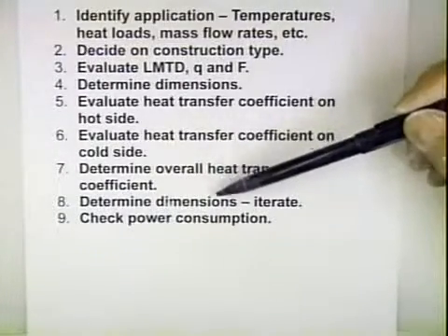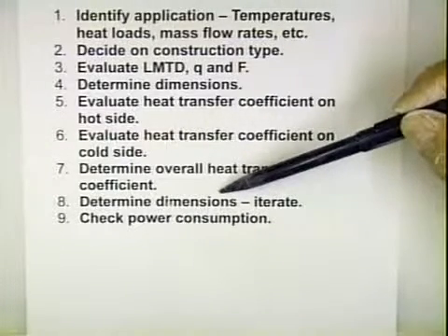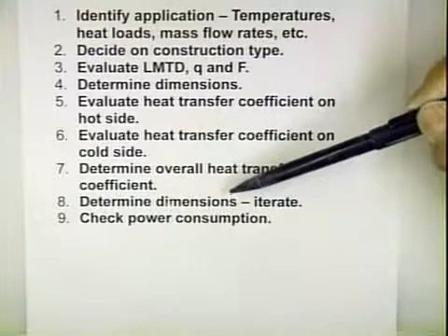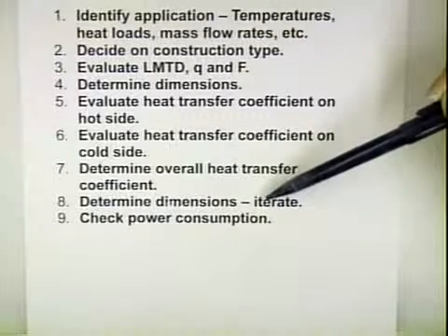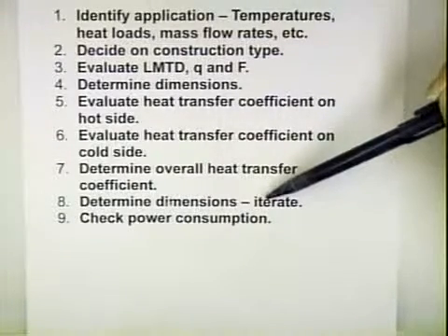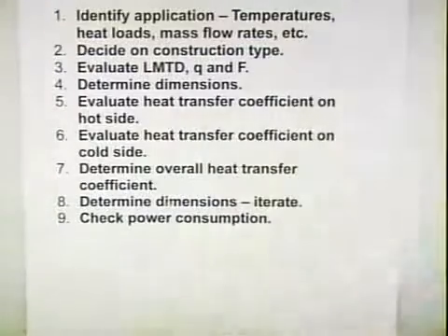Once we'd done that, it says determine the dimensions, and the only dimension left for us to determine was the length in this case. It turned out that the number of baffles based on our process was not a whole number, so we had to iterate until we do get a whole number, and then finally we check the power consumption.